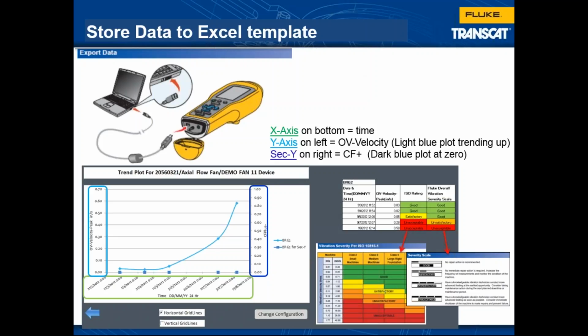We can also compare this to ISO standards. There's an ISO standard, 10816, that is used in general industries. It really only has 4 categories: small machines, medium machines, large machines, and large machines with a flexible foundation. So it's not as specific as the 37 categories, but it is an ISO standard, and it will help you determine whether the machine is healthy or not.